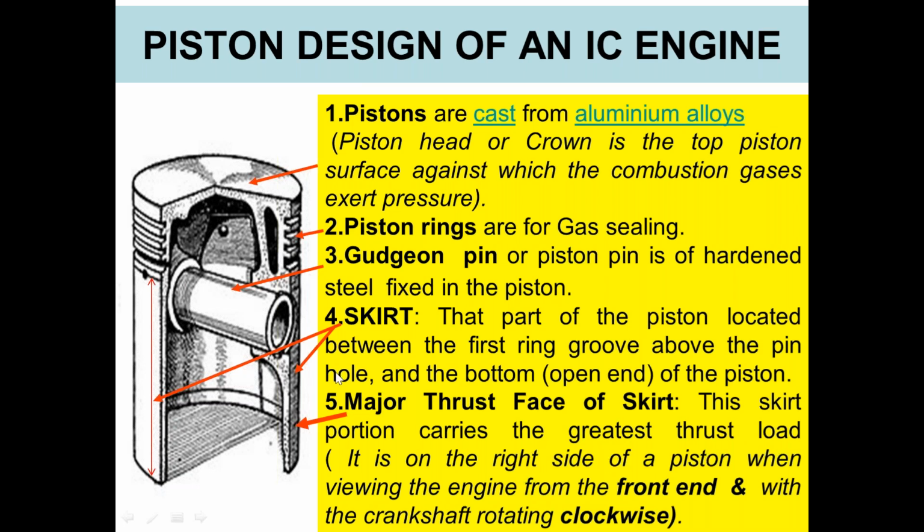It is on the right side of the piston when viewing the engine from the front end with the crankshaft rotating clockwise. This is the clockwise rotation. Then this is the right side of the skirt, and this is the major thrust face. Here, the greatest pressure is exerted on this face.